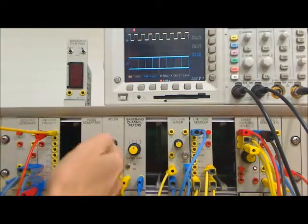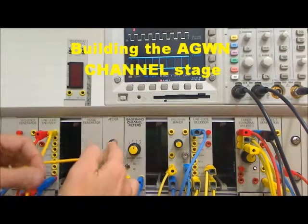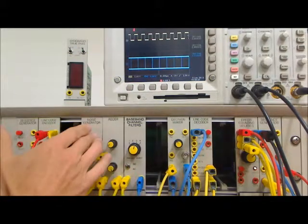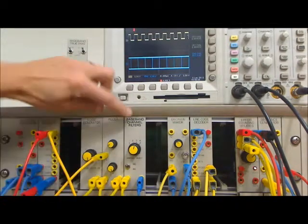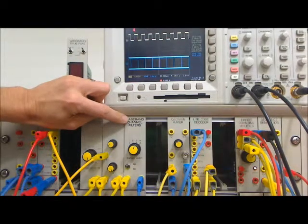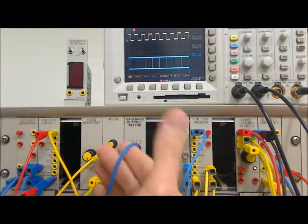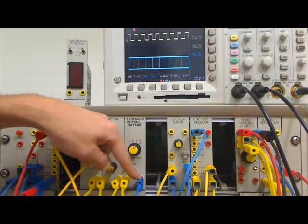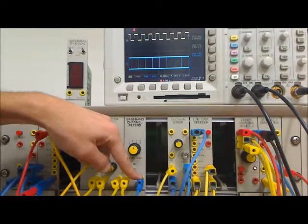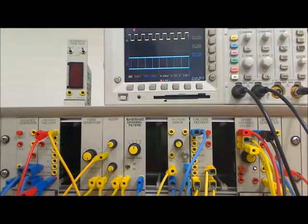We take the line code signal and input it to the adder. The adder makes up the channel. Into this channel we add noise from the noise generator module, and the output of the adder goes to a channel filter, the baseband channel filter, used to restrict the bandwidth of the baseband channel. Then the output of the baseband channel filter at this point is connected to another adder in the macro model in figure 5 to adjust for any DC offsets. However, in this demonstration we won't worry about DC offsets,